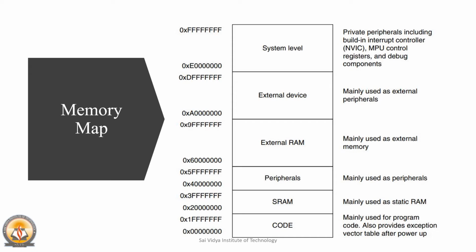The Cortex M3 design has an internal bus interface optimized for this memory usage. In addition, the design allows these memory regions to be used differently. For example, the data memory can still be put into the code region and the program code can be executed from the external RAM region.